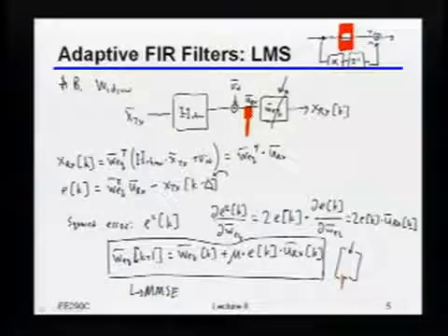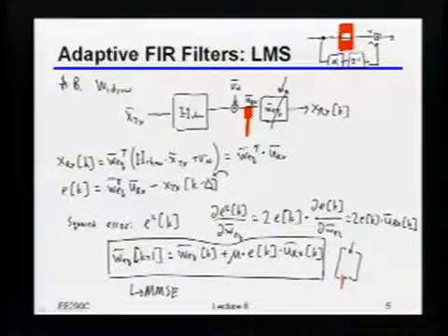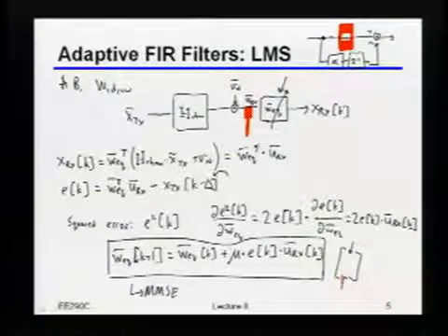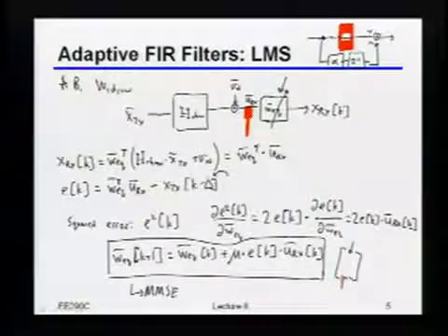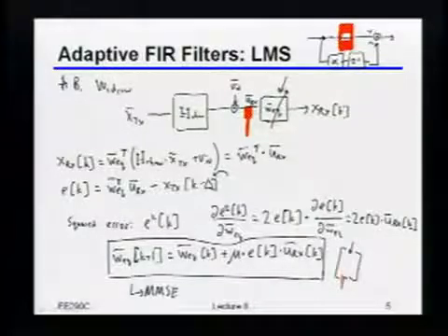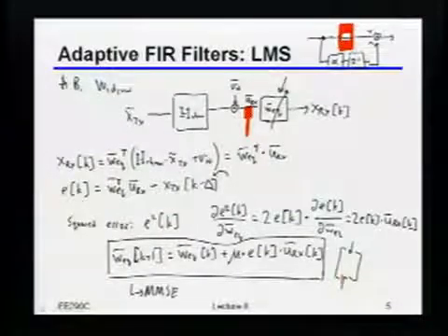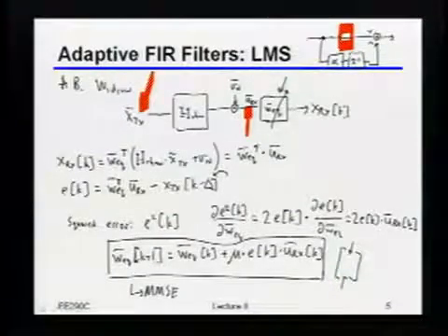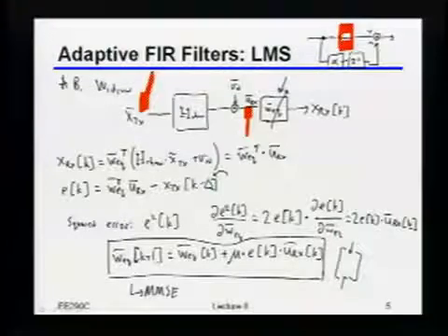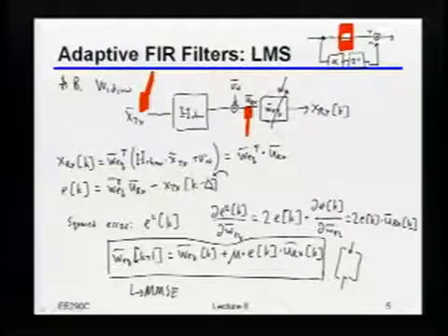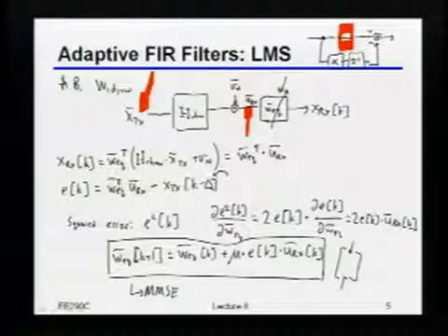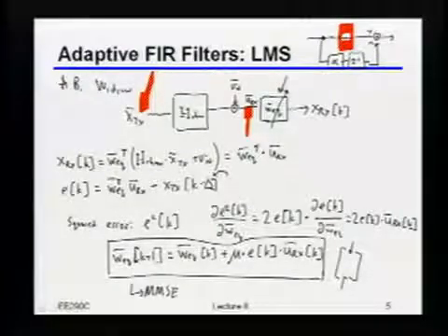Okay. So make it clear. tx is a vector, for example. In your case, if you assume it's a pulse, it's 0, 0, 1. No. Okay, so just to be totally clear, this xtx here is not a single bit. It's my actual data stream. So then what is xtx k minus delta? It's just the bit stream shifted by that delta.